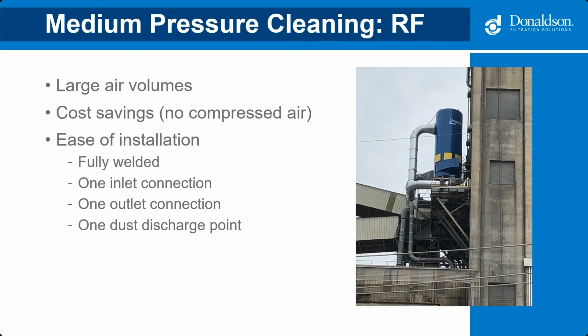These bags are cleaned on a medium pressure system that's produced by a PD blower. Thus, it saves money on compressed air. The other advantage to an RF in this type of situation, up to about 400 or so bags, is a quick and easy installation, as they come fully welded, so the units can be lifted straight off a truck with a crane and put into place with minimal installation required outside of that.